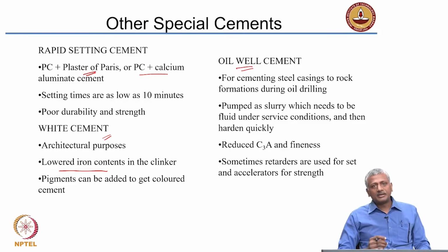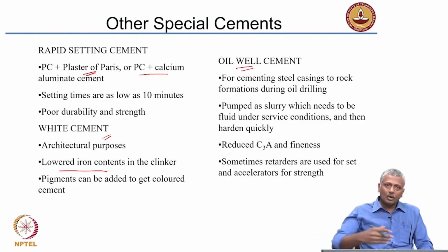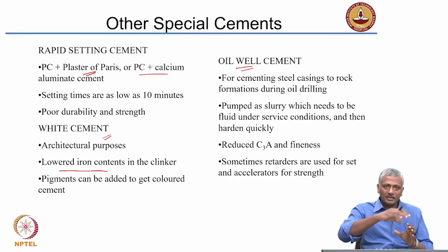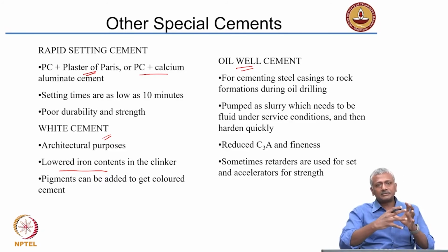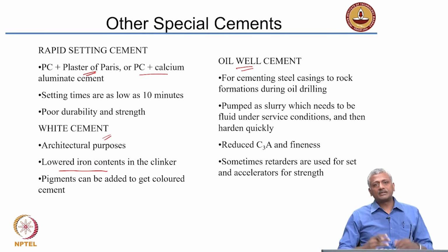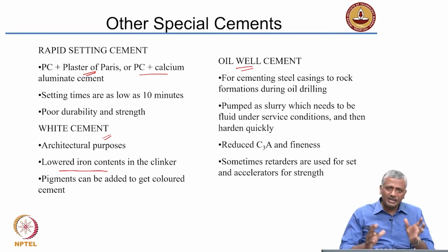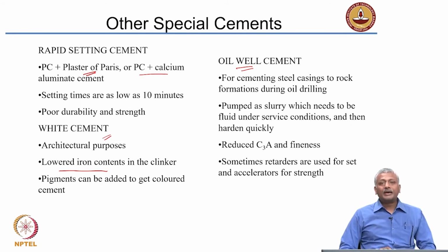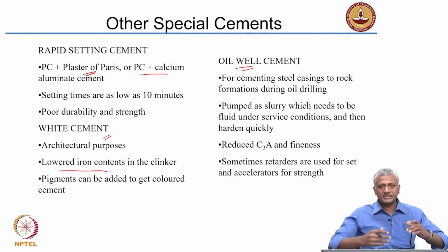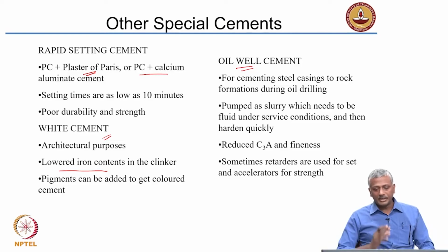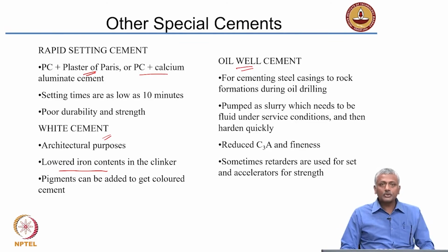The cement should be such that it can flow very long distances after mixing, but at the same time when it comes to rest, it should form a layer on the soil surface so that the soil does not cave in. So it's a very uniquely formulated cement and it needs a combination of different types of additives to ensure that it is flowable for a long time, but when it comes to rest, it sets and hardens almost immediately. Again, this is something that needs to be formulated very carefully.